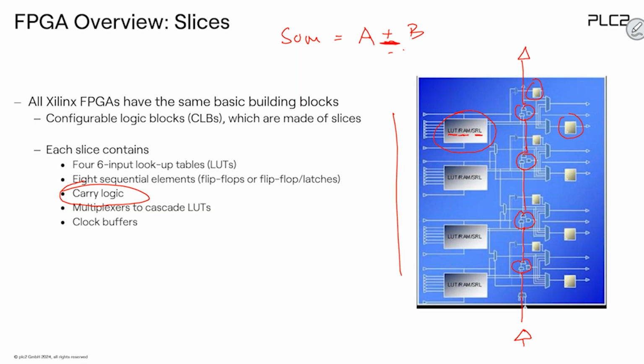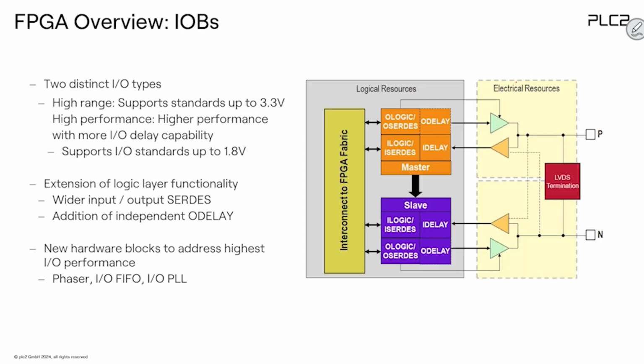So this means whenever we describe something like this, the synthesis tool is clever enough to place and implement this carry generation structure inside this very special structure inside the slices. This helps very much to reduce the overall complexity of the FPGA.